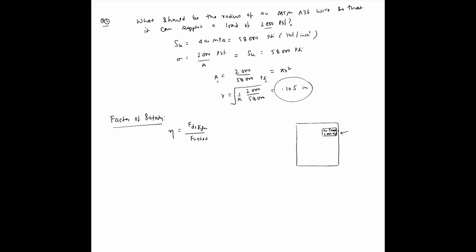So over here, this thing is called rated load. 2000 kilogram is the rated load. Now, factor of safety allows you to create your design in a way so that even if your actual load exceeded the rated load, you will still have some buffer, okay? So if let's say the factor of safety was 2, then the design load would be 2 times of the rated load, right?